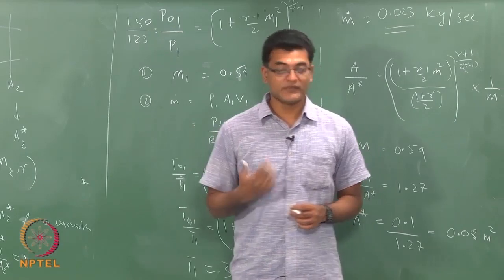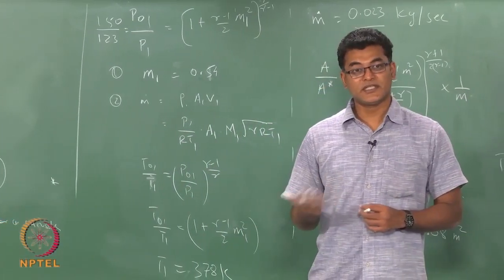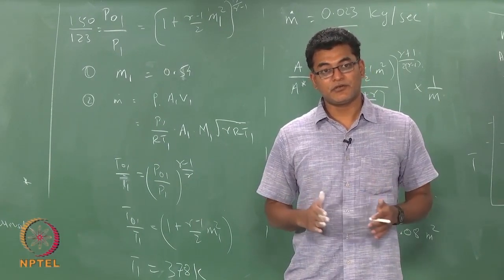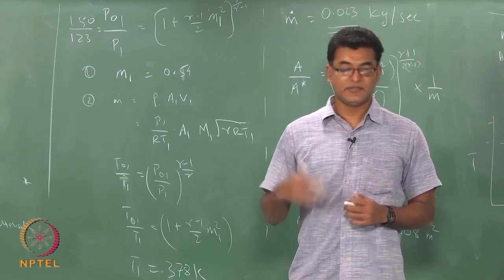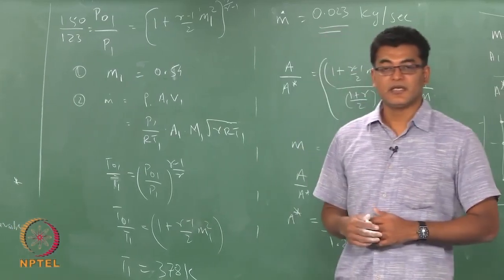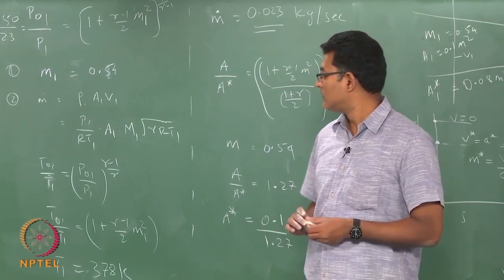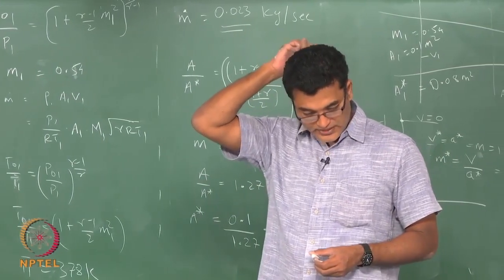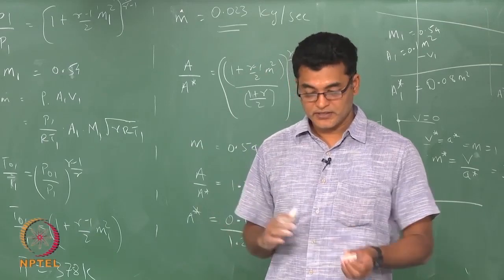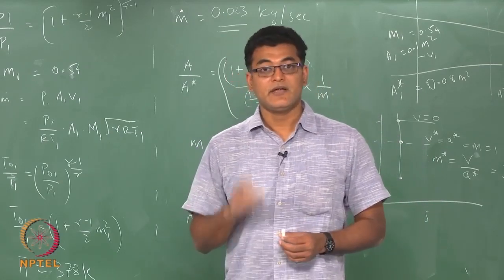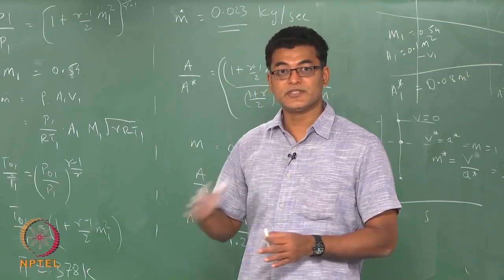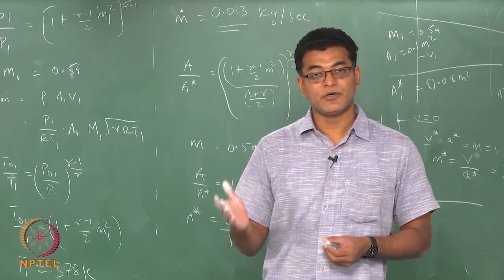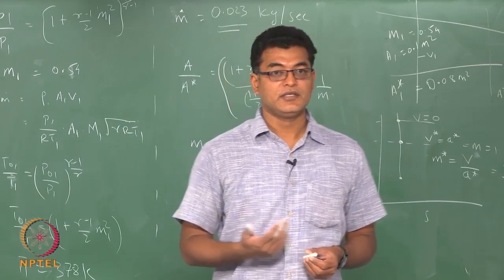This has more implication when we discuss converging diverging nozzle. So, what should be your entrance area, what should be your inlet area, what should be your throat diameter, everything is decided by these quantities, which we will see in the classes later on. Okay. So, what we have learned now is the meaning of A star, how you can relate that to stagnation temperature, Mach number, stagnation properties, relation, everything. We will do exactly the same problem using gas tables at a later point. Okay. So, we will discuss something more on A star and then we will use the gas tables.